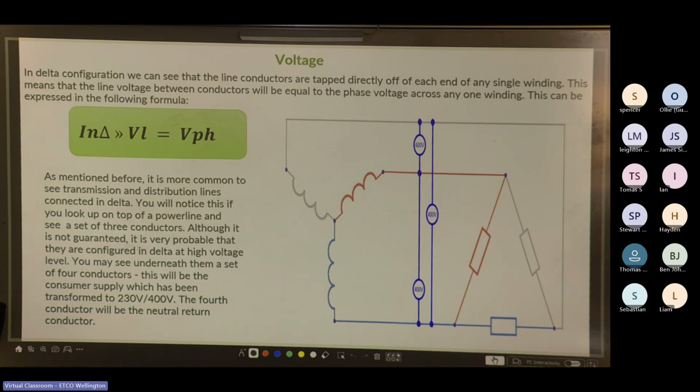So if you ever look at a street pole and you see levels of wires, if you see there's only one set and there's 3 wires, it means it's high voltage, stay away. If it's 4 wires, it's low voltage, but still don't mess with it because it is the distribution network. And the lineys are very, very titchy about us Sparkies working on their network. Unless, of course, we happen to be a linesman as well, which I'm not, so I don't touch it.